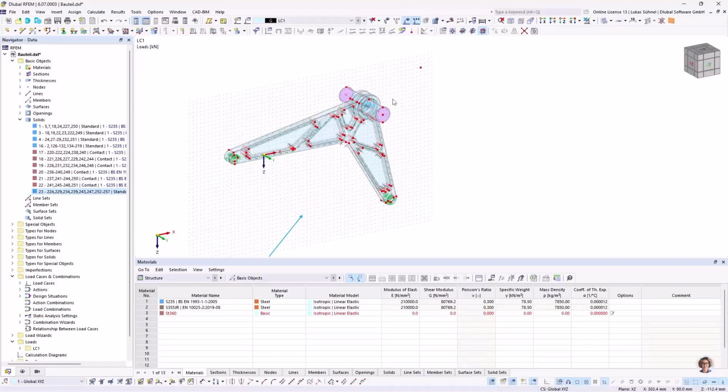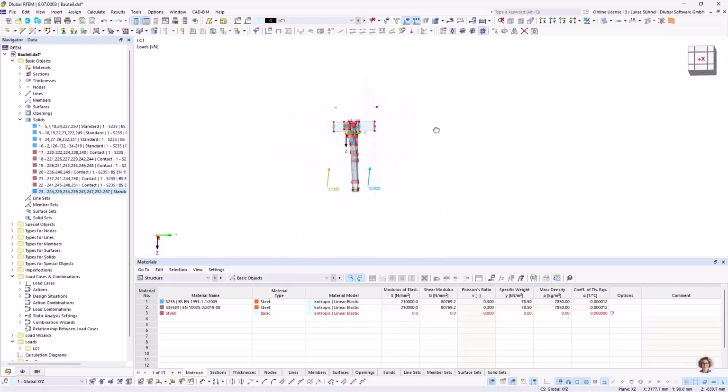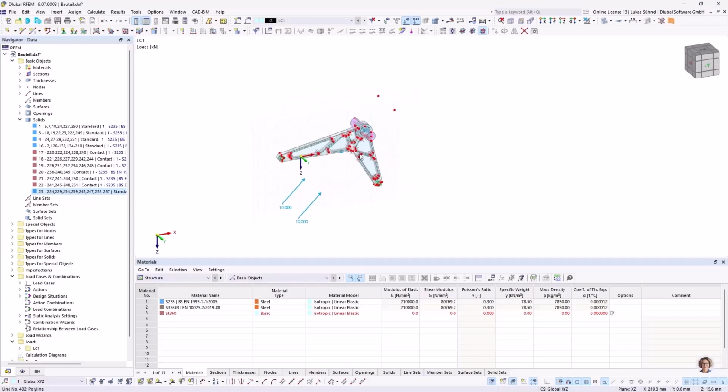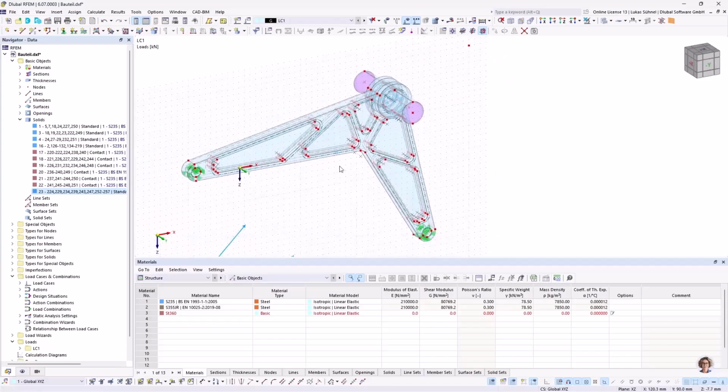or anything like that. Now I select my load, one more time this point, and also this one. And I use drag and drop to put it to the other side, to copy it to the other side. And again, I already have a correct defined nodal load. Yeah, so far regarding the modeling and the loading.